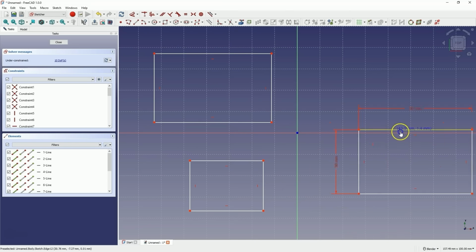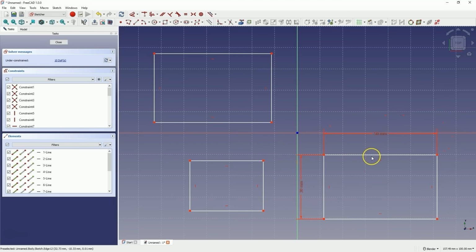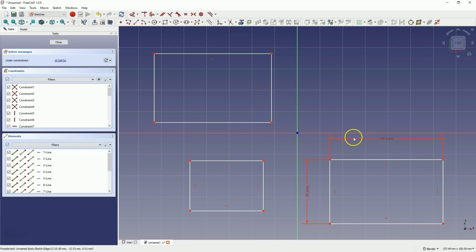In this case, we can only change the position. The dimensions are already strictly defined. However, this sketch is not correct because, as I mentioned at the beginning, when creating a body type part, it must be one single solid, and based on this sketch we would create 3 solids because these sketches are not connected. Therefore, we don't do such things in FreeCAD.